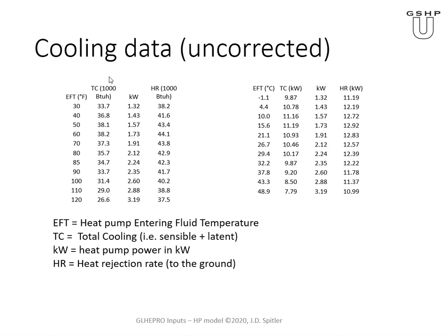And of course, you probably realize that as conditions change in the space, say the humidity in the space or the humidity entering the unit changes, the actual amount of latent heat transfer will change. The manufacturer has a way of correcting for this, but it doesn't really extend to a model that, certainly with the approach we're taking, could readily account for changing inlet conditions to the unit.